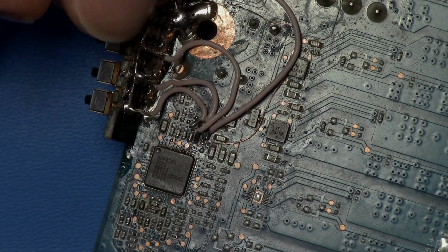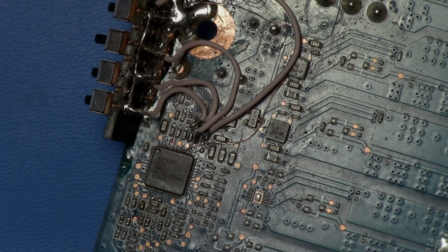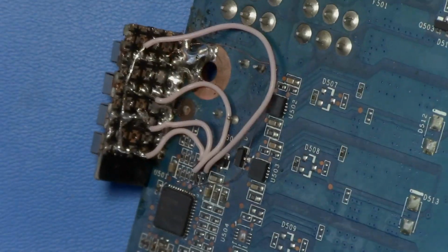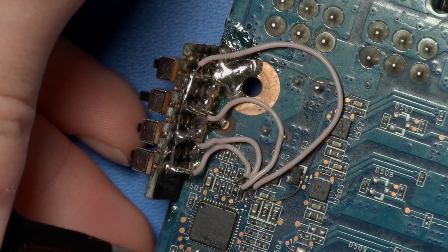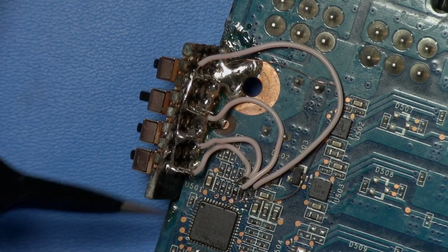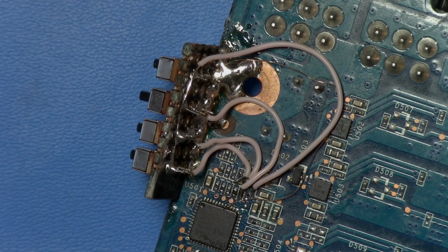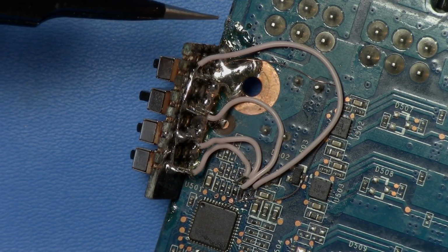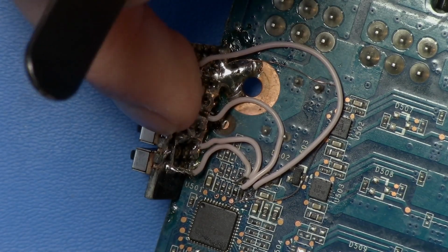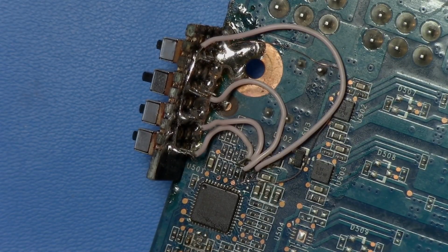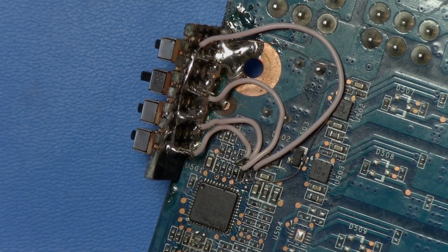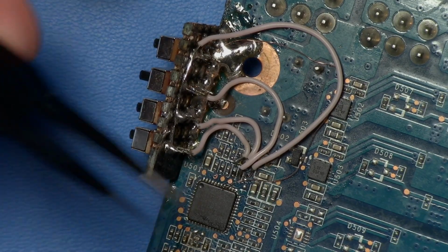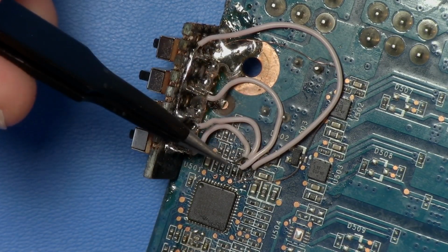These are single pole dual throw switches. If you have single pole single throw, it works the same way. The dual throw ones, you just leave one side empty. This is actually the edge of the PCB, so this entire edge on both sides here is all ground. So I just basically scratched some of that away and soldered this directly on, so it's held on even more firmly than if you hot glued it, which is kind of nice. And yeah, you have your 3 little wires here that go to each of those resistors.